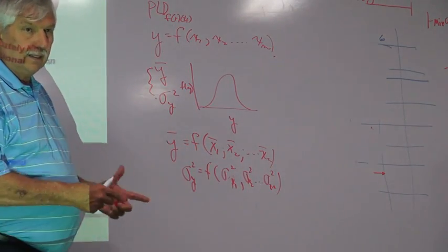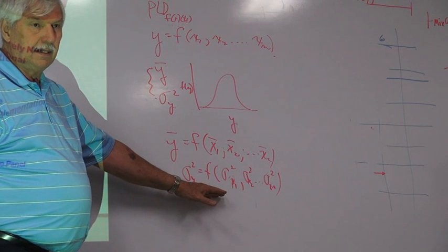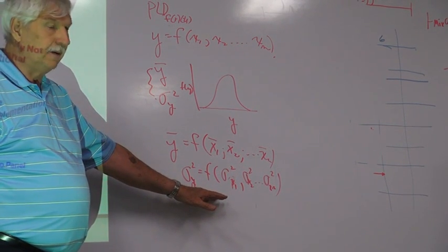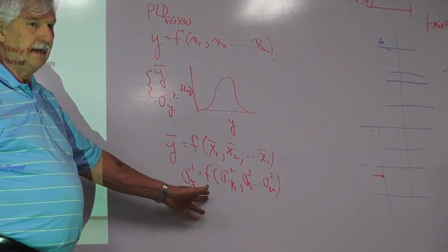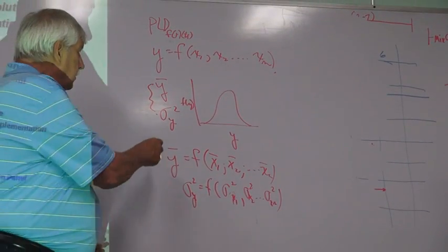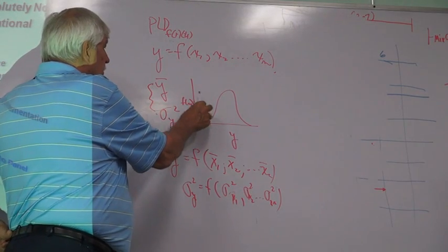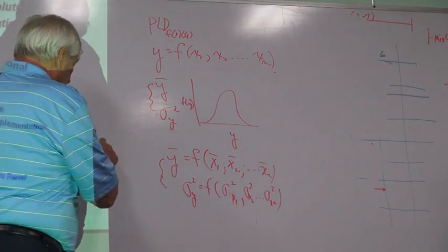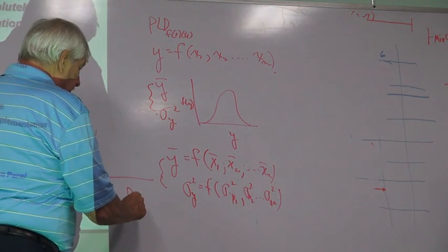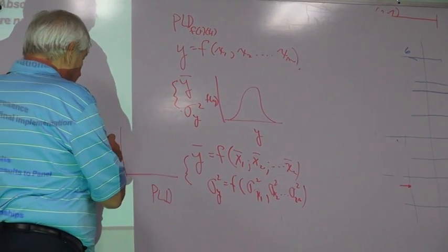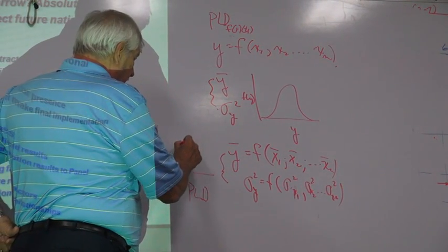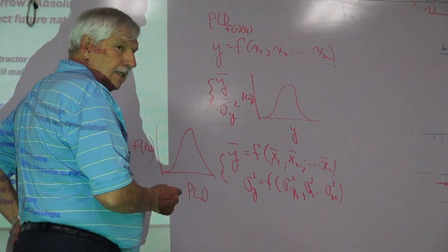So mathematically, we can model these by Taylor series or beta distribution or Rosenblueth, for example, for every one of the variables. I don't get a single solution for the predicted life. I take all of this and get a distribution of predicted life difference, PLD, and what I generate looks like this.